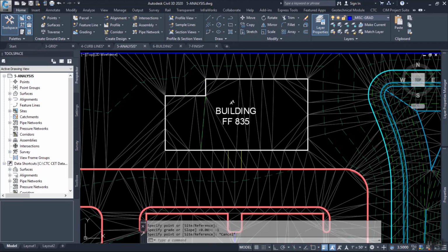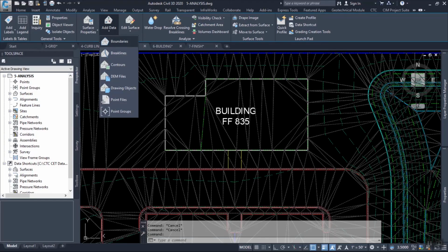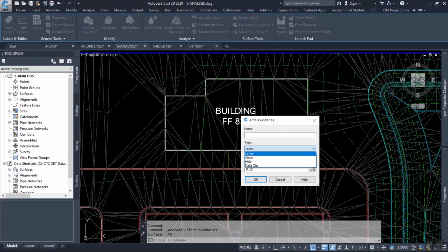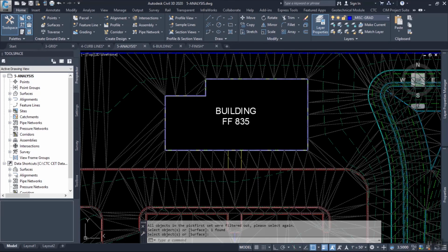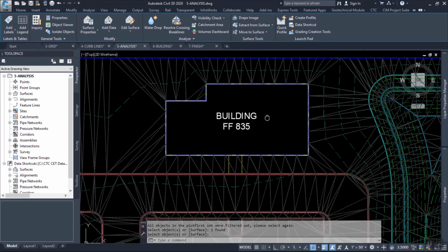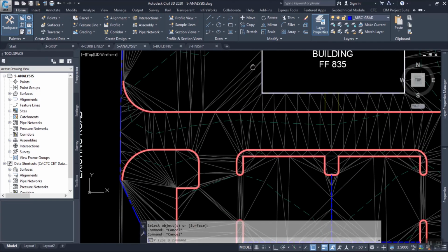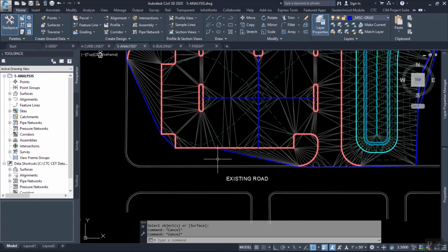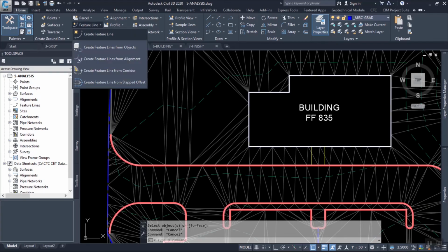Okay. Use that same feature line to poke a hole in your surface. Do a hide boundary for the building to poke a hole in it. Okay. Same thing down here. Grab your feature line along your existing curb there, or wherever your grading limits are going to be. What about areas like this, little miscellaneous areas?